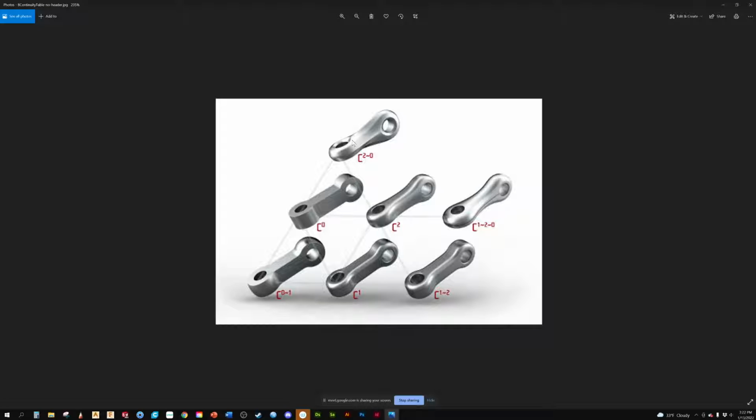They're still radiused. Everything is still very smooth, but you're going to start getting some tangent breaks in there. SolidWorks does C2, which is curvature continuous, and it does C3 now, and we'll talk about what C1, 2, 3 is a little bit later. But it doesn't do it very well.